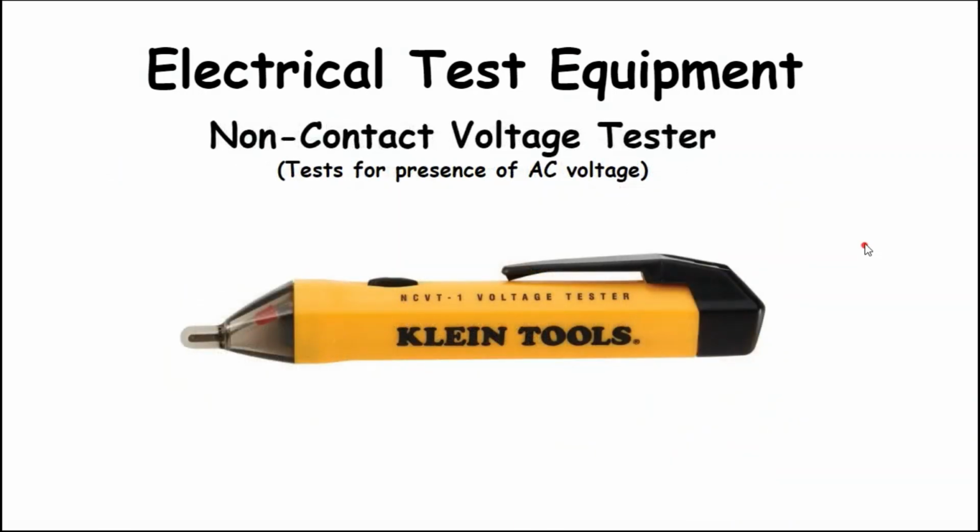A non-contact voltage tester is something that I recommend technicians have. I use it all the time. It tests for the presence of AC voltage above ground, and among other things, can come in very handy for doing point-to-point troubleshooting when you don't want to have to connect a reference lead. This is also very useful in just generally testing whether circuits are live, which can be a real time saver.